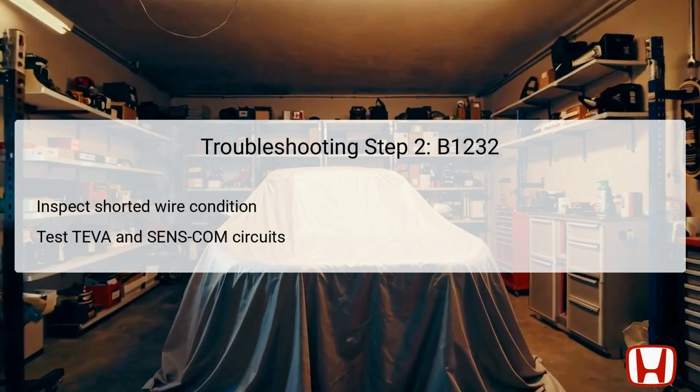The second step in troubleshooting DTC B1232 focuses on inspecting the external circuits connected to the evaporator temperature sensor. This includes checking for any wires that may be shorted, particularly in the TEVA, Temperature Evaporator Sensor A, and SenseCom, sensor communication circuits.